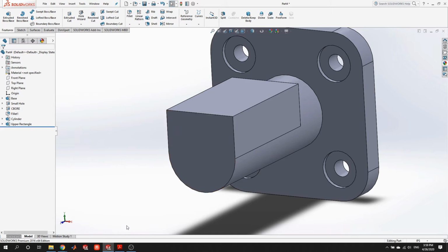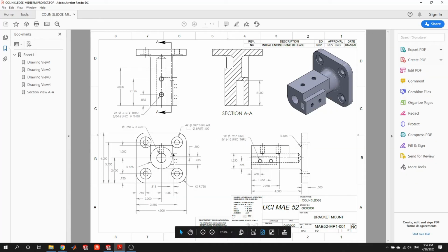The next thing we're going to add is the side rectangle. So we see this right here. Okay. Now this one's a little bit tricky. So the dimensions for the width here, we see that it does meet up tangent with the bottom of the circle, but for this width or height, however you want to think about it, it's 1.25 inches. And then the depth of extrusion is still shown in this drawing, and it's 2.25 inches.